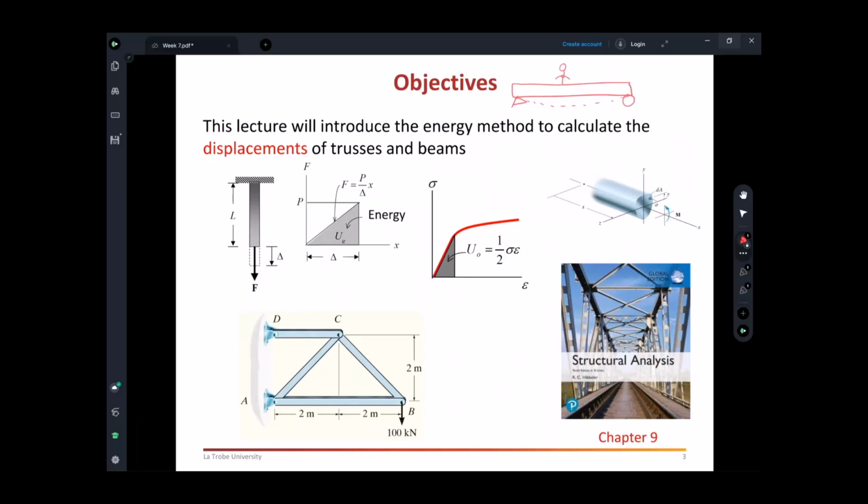The word serviceability is used in design. Serviceability means that your structure should be serviceable. You can design the structure to be safe, meaning that if users are using your structures, beams, and slabs, it is not failing. But if it is deflecting too much or vibrating too much, the users are not able to use that building because it is not serviceable. So we need to make sure that the structures are safe and serviceable.